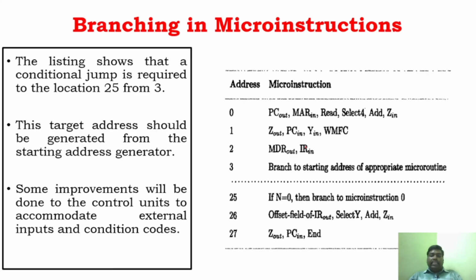So if this is the branching instruction, what it will do is calculate the effective address, and it will add it to the updated address in the program counter. We have just seen how it calculates the new address of the program counter, and then how it is sent to the program counter. We have already explained this in the previous video, please go and watch, okay? And as I said, this 3 once again is a fetching instruction.